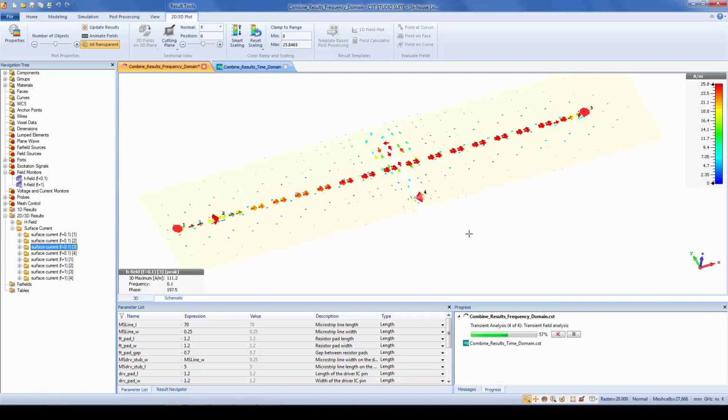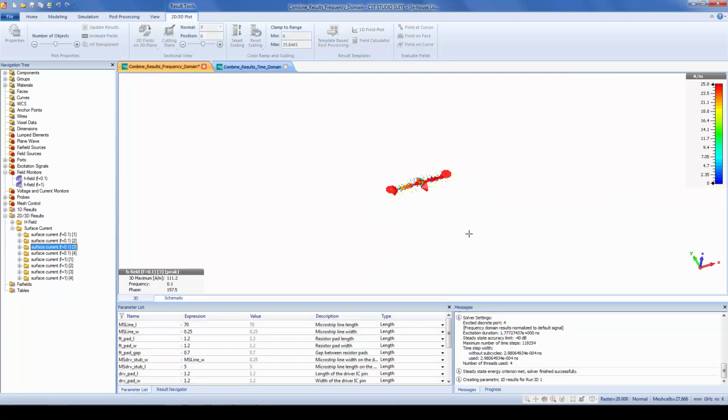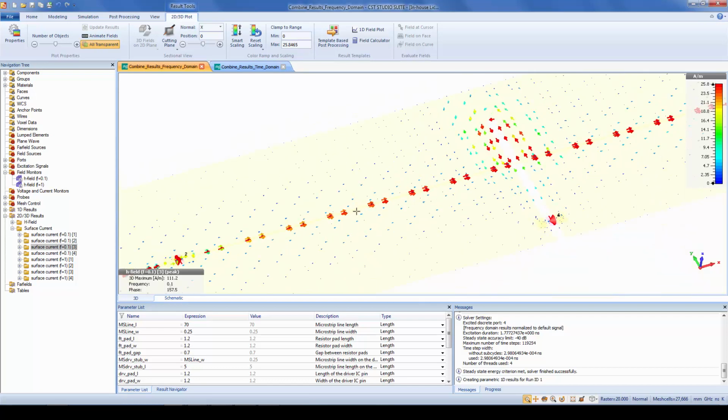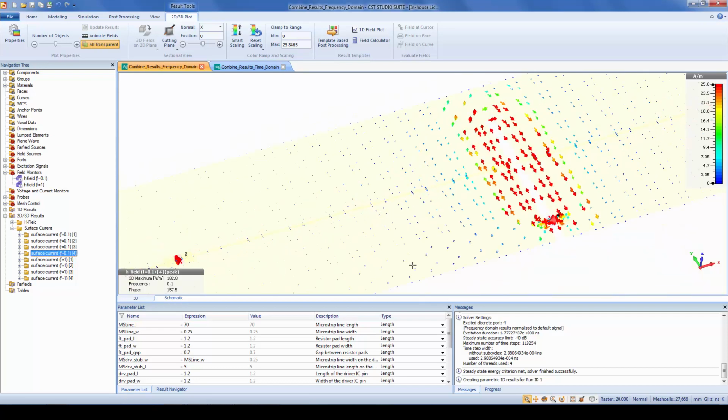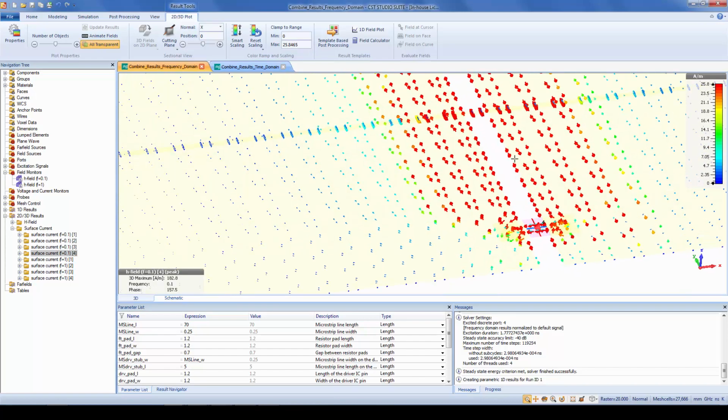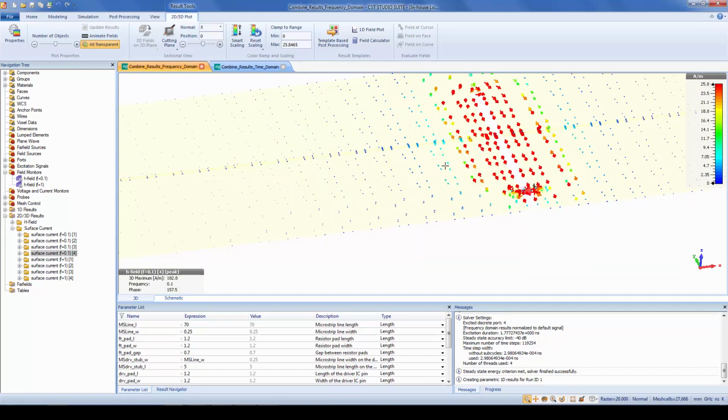So what I get is the surface current or the electric field, whatever field I want to see, for each port separated from each other. This is not an overhead to a standard simulation, because this is the same approach that I need to choose if I want to calculate S parameters. So once I have calculated this broadband setup and all the field monitors, you can see of course that port 4 creates a pretty different current distribution than the other ports, because it's placed here.